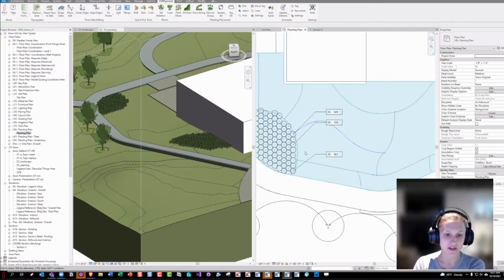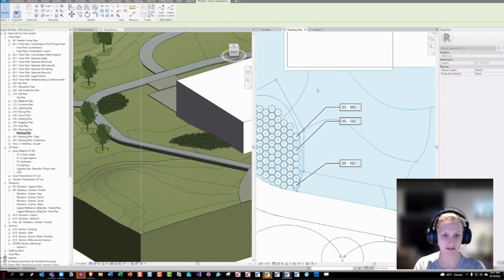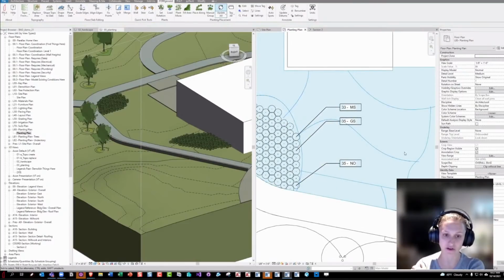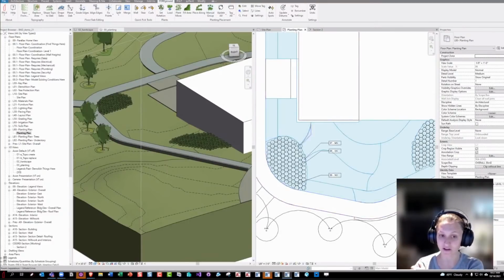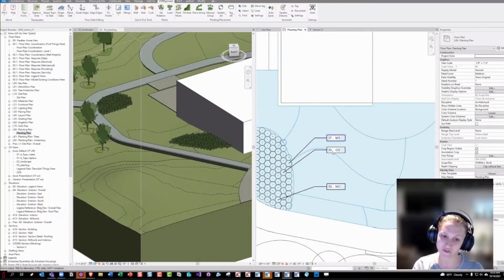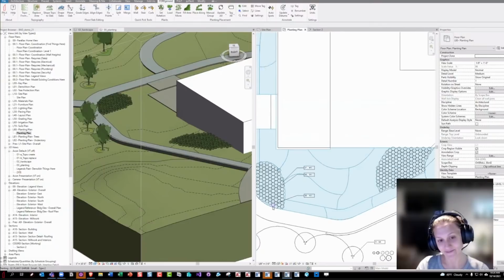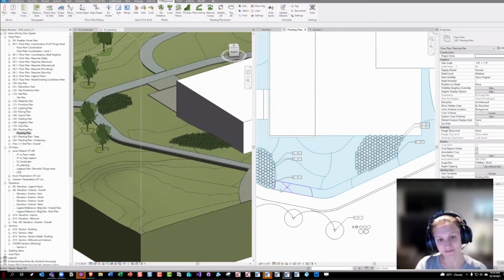If I change the shape of this and do another update all, it's going to try to keep those tags in the same place, effectively. Every time you run an update on the ones that have been placed automatically, it's actually going to replace all of those, because if the shape has changed, it needs to replace them, so it has to retag them all. But there's some stuff happening so that we keep track of where this stuff is, so it looks like it doesn't move on you. That's awesome. That seems like something that'd be super useful to anyone who has to do that.